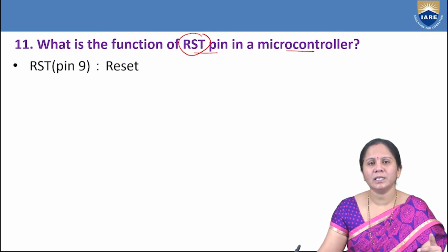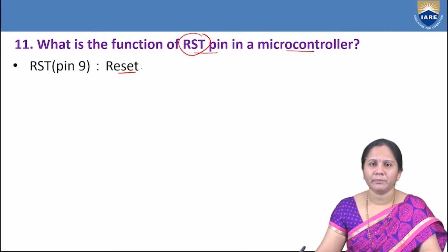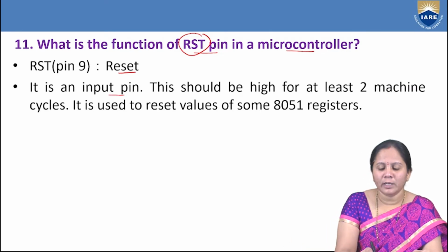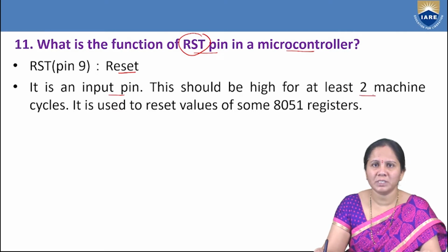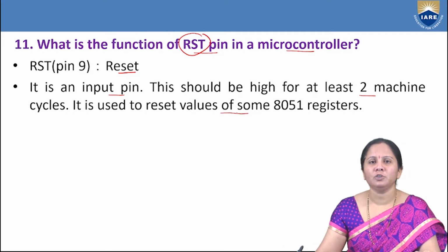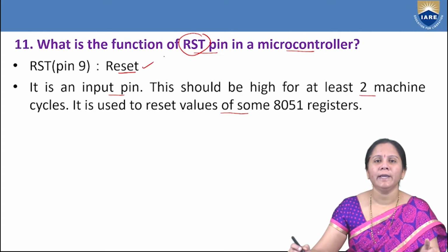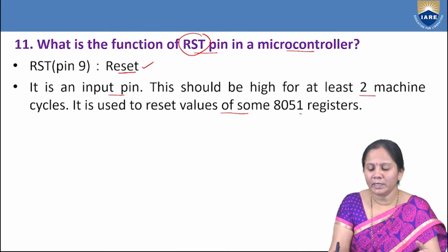It is the 9th pin among the 40 pins. It is an input pin. This should be high for at least 2 machine cycles. It is used to reset the values of the 8051 registers. So generally when this reset signal is enabled, all the registers that are available in the 8051 microcontroller will get reset.